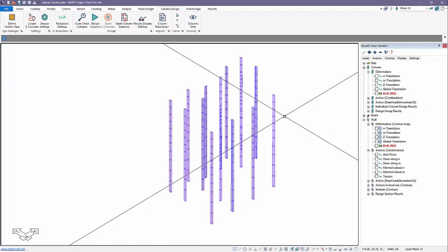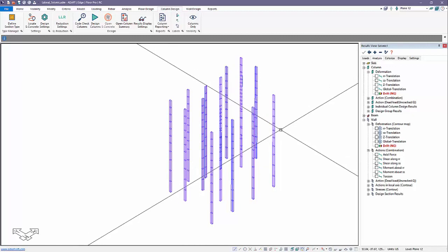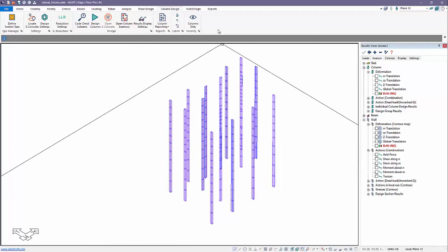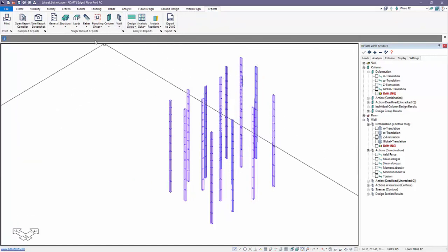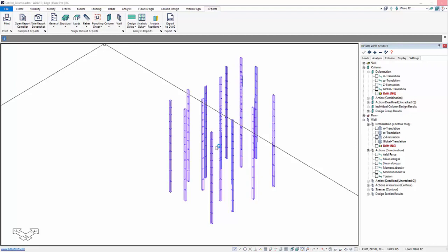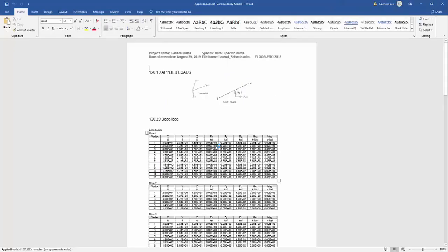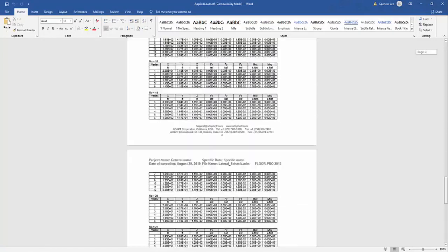For determining the center of mass and also the story forces that the program actually calculated, we can go to reports. Under reports, we're going to go to the loads option and applied loads. And the applied loads report is going to actually show us and tabulate the base shear, all of the different seismic coefficients and parameters that we entered, and also the story forces that are calculated. So this gives a reporting of that.